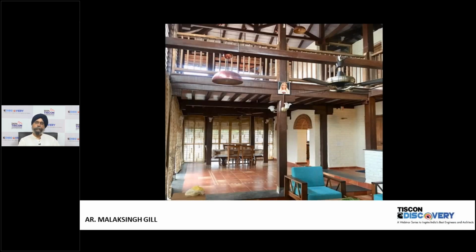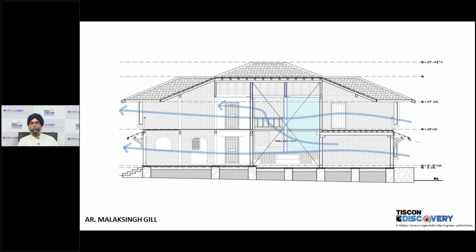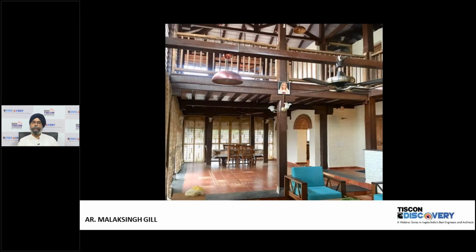This is how the central space rises up. You can see the whole framed part of it. The load bearing part is to the right. The left side is the entire framed building, which has timber frames. Here we have also used some steel columns, because we have sited the water tank within the building. If you see the top central area, that is the water tank. So in the center, we took two steel columns to be able to make a floor above to take the water tank.